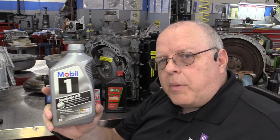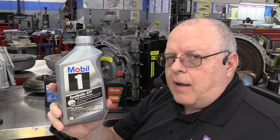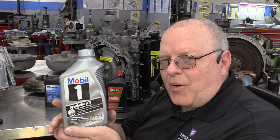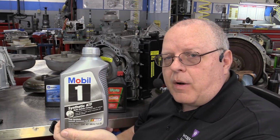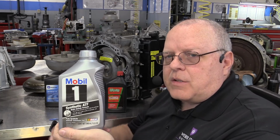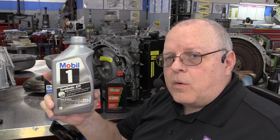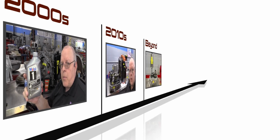So buyer beware. They're not lying to you, but you need to read the fine print, and you need to understand when these fluid specifications even came about, because if you pour the wrong fluid in your transmission, it can affect how it operates and the life of that transmission. And it won't necessarily cause a failure today, tomorrow, next week, next month. It might cause a failure a couple of years down the road that might be several years sooner than it should have been with the proper fluid.